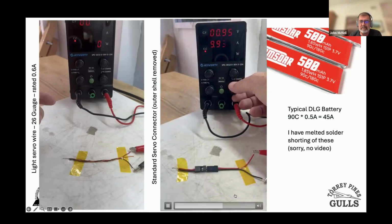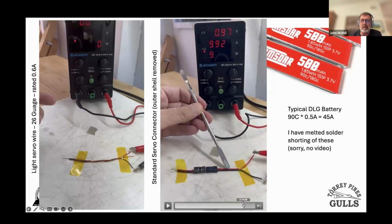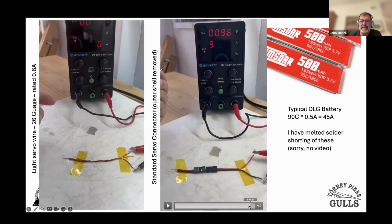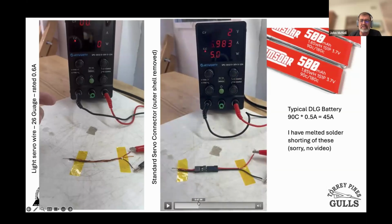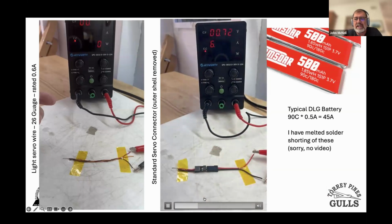I know I'm fast forwarding it. So basically, I'm testing the wire. The wire is totally fine. This is 18 gauge wire. And somewhere in here, I touched it. Where did that go? I'm sorry, I skipped that. At 7 amps, it was hot enough that I decided not to touch it anymore. So if it's rated for 3.5, at twice the rating, it's too hot to touch.